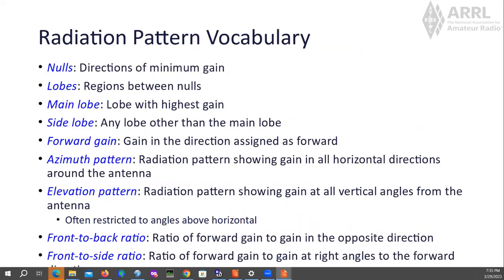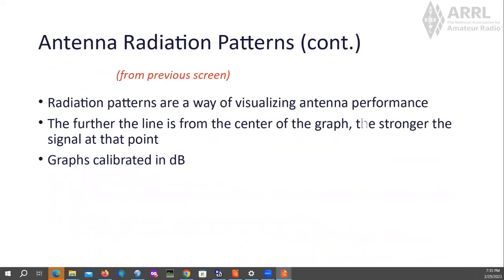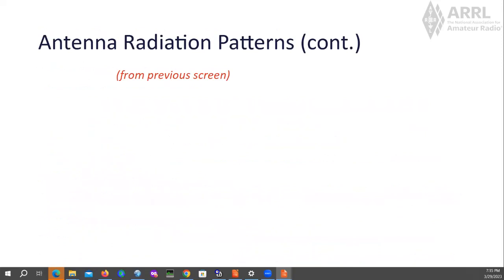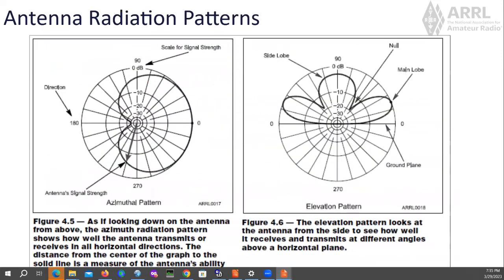Was that example diagram possibly of the same antenna, just from different viewpoints? That's exactly what it was. You wish to go back? Yeah, just for a second, if we could take a look at it so I can understand. Okay, take me a second. So this antenna, I think, is set up feeding two verticals that are about a quarter wave apart. In one direction they cancel, and in the other direction they are enhanced.